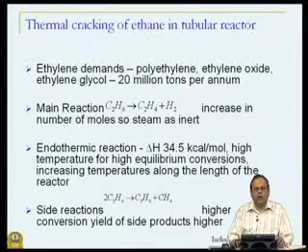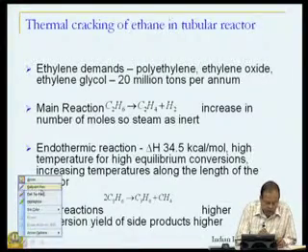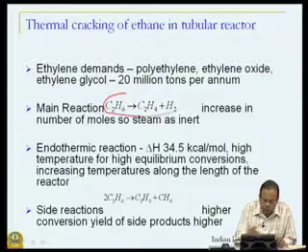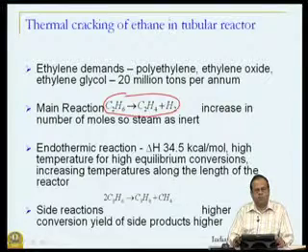So, what is the main reaction here? So, the main reaction for this is the cracking of ethane. So, ethane molecule C2H6 gives ethylene C2H4 and another molecule of hydrogen. Now, if you look at this reaction, clearly starting with one reactant mole, we get 2 moles of product. So, there is an increase in number of moles, and it is a gaseous reaction.